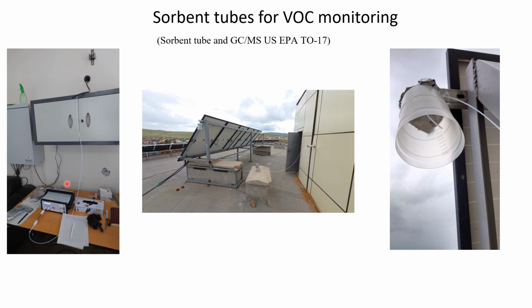The left side shows, in the small monitoring room, we put a pump here and connect the tube, connect with the Teflon line, Teflon tube, and go to outside. And outside, we fix the shelter and the inlet like this.